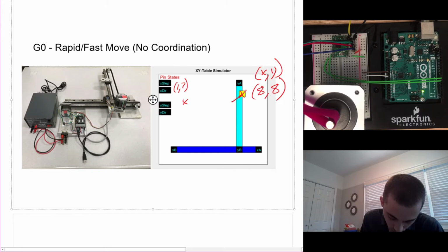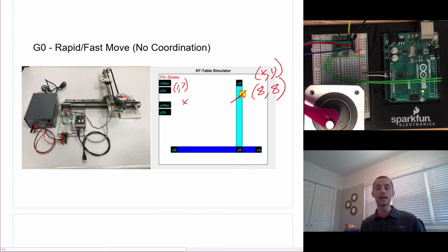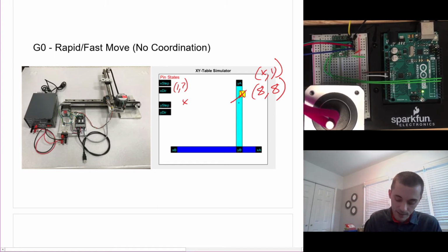It's going to do the one node thing, downward at a diagonal, both motors moving at the same rate because they're the same motors with the same pulleys, same belts. You'd see a diagonal movement where they're moving at the same rate. And then we would get to a point where the Y coordinate after 1 inch is equal to 7 inches. And so it is done moving.